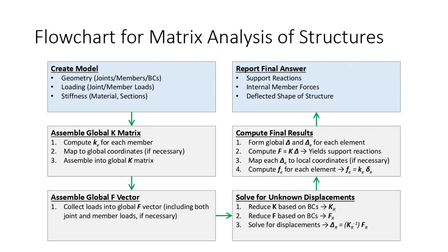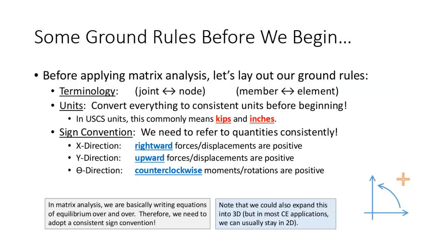Once you have the displacements, you take those displacements and break them down into little displacement vectors for each element. And if you've got the stiffness matrix for each element and the displacements for each element, just multiply and boom, you've got the forces in each element. So the idea is, you collect the system into one big matrix, solve for your displacements, take those displacements, and plug them back into each element. And then that's it, the entire problem solved. So there's a very algorithmic process, if you will, where you can take a model and solve the entire thing out in one straightforward process. Now, you're going to find that this is really straightforward, and I've got a really simple problem today to sort of